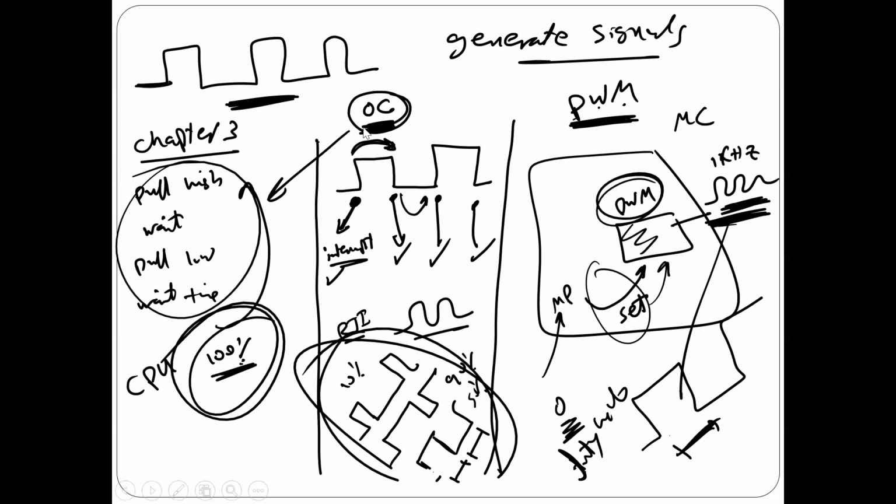The other idea is that you can use interrupts in case of output compare. So here, as I told you, have an interrupt here, an interrupt here. In every interrupt, you have to write some commands to set the time for the next toggle, right? As you will see. So here, this one is much better than this one, because all I need is a little time here, a little time here, a little time. And this is similar to what you did in test 2.